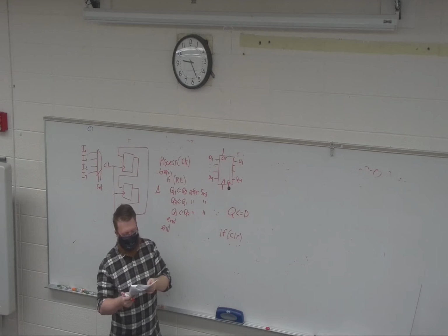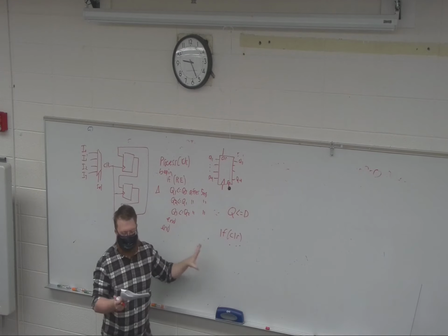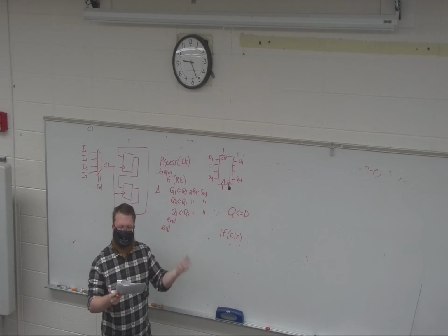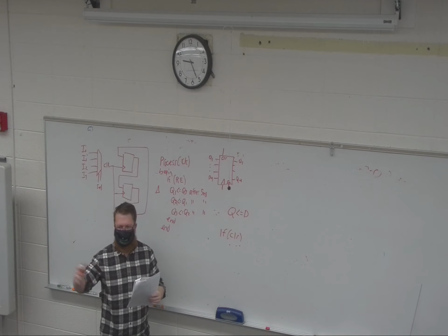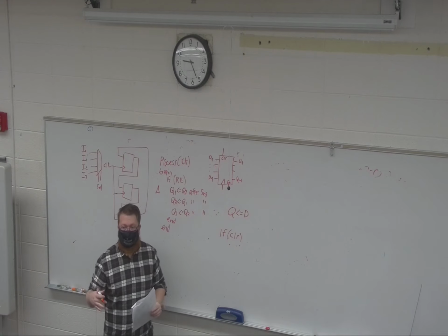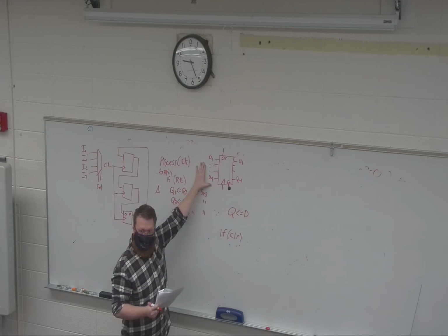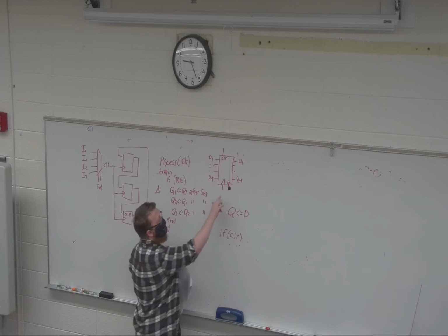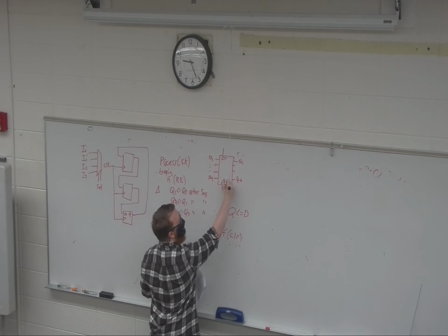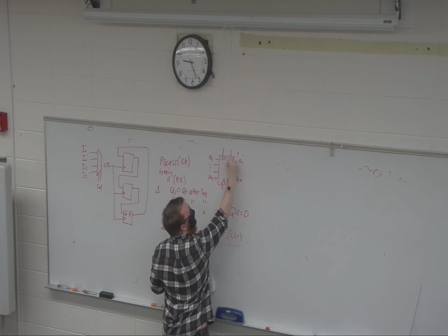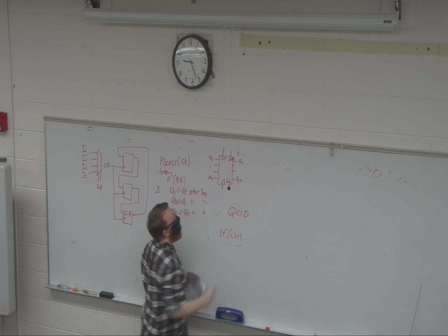There's also an example of a left shift register in here that I won't go through just to keep it going, that shows you how to bring in new data and step through. And you can write it 2 different ways. You could have essentially this guy as a shift register, and instead of just, we'll call it load for now, instead of just load, I would also have shift.